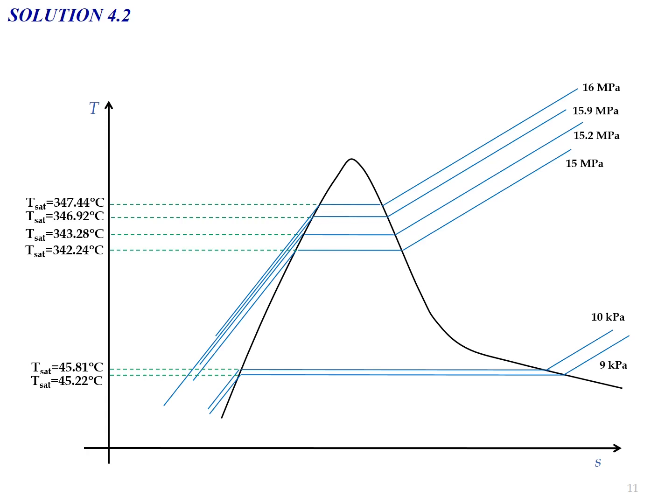And then you need to plot each specific state by referring to the temperature given. Because we know that the temperature for state number 1 is 38 degrees Celsius and the phase is compressed liquid, because the temperature is below its saturated temperature, state number 1 must be below the saturated temperature of 45.22 degrees Celsius.